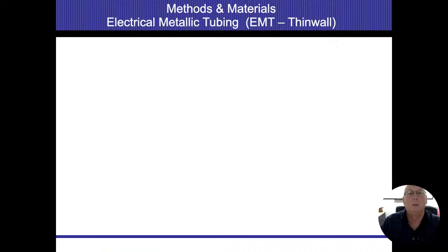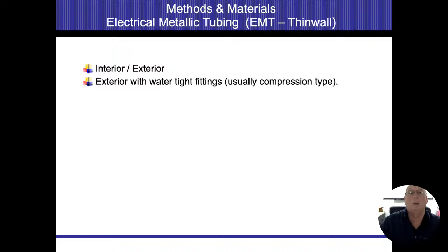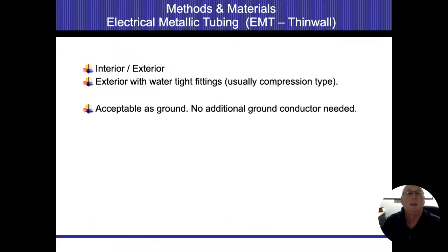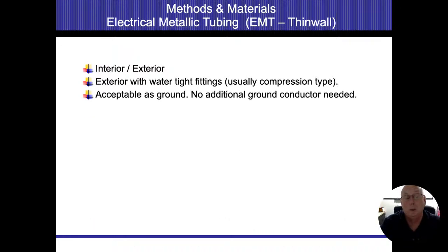EMT. So EMT could be used interior and exterior. Exterior has to be with watertight fittings, the compression ones. It is acceptable as a ground. But this is a big deal. So we don't have to have a ground wire inside of them.